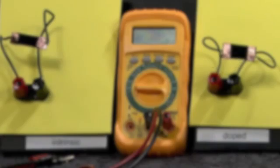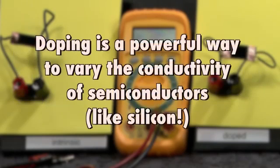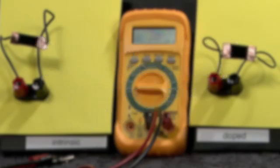Today we learned that we can use doping to control the conductivity of semiconductors by changing the number of mobile charges in the material. When we look at the range of conductivities that silicon possesses, it is truly amazing. Through doping, we have a very powerful way of varying the conductivity of semiconductors. This is something that is not possible in other classes of materials, like metals.